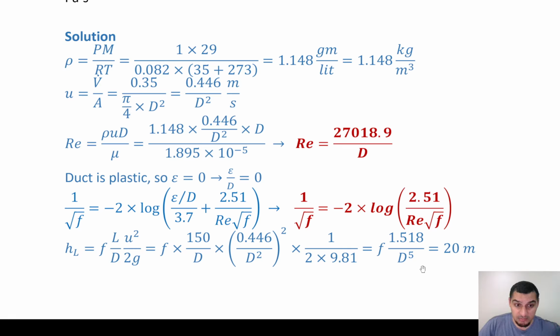Okay, it was diameter power 4, which means that, as we said, if the pressure drop is, let's say, 1 atmosphere and the diameter is reduced to half, then the pressure will be 2 power 4, so it's 16 times. So it's from 1 to 16. This is in laminar flow.